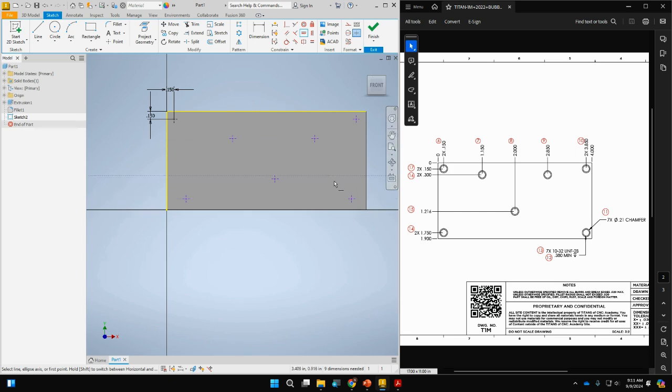You didn't see much of a movement because I kind of placed them that way. But basically what will happen is if one moves, the other moves. You can see them kind of move together. Right? With that, I'm also going to add some vertical constraints. Right? These two are vertical to each other. These two are vertical to each other. So I'm going to click my vertical constraint, make that mark and that mark vertical, this one and that one vertical. So that kind of moves them over.